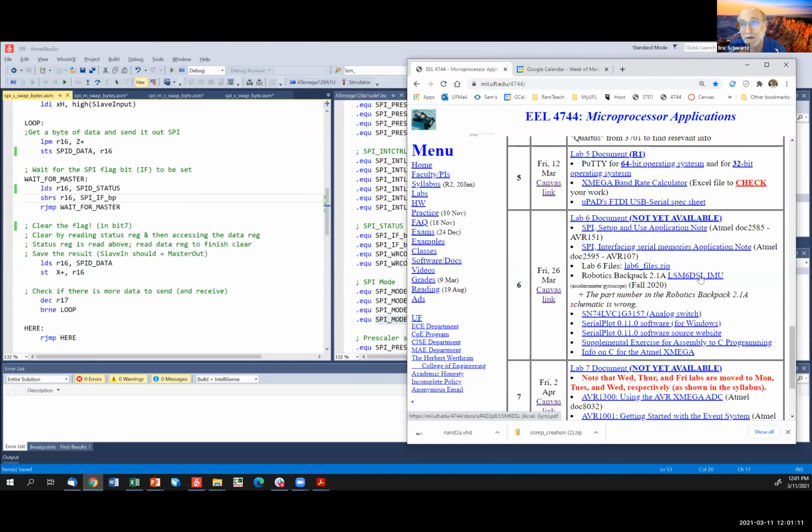This is an external device that has control registers you're going to write to. Just like inside your processor, there are control registers, except we're not connecting this with the EBI system. So we're going to write the control registers by sending an address from your microprocessor, which is going to be a master.